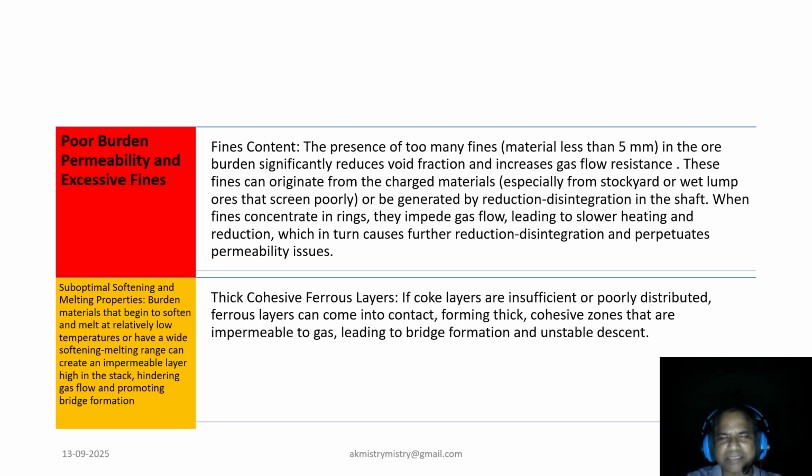Such fines are generated in a temperature band of 500 degrees centigrade inside the furnace. So these two phenomena of generation or ingress of fines are to be looked into. They form a concentrated ring inside the furnace, impeding gas flow and perpetuating the permeability issue on a drastic scale. It is difficult to run the furnace in such a situation.